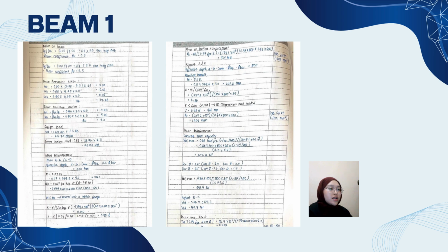For the shear force, lastly we check the shear resistance. We first ensure the concrete strut will not crush by calculating VRd,max at both 22 and 45 degree angles. The concrete capacity is much higher than our maximum shear force of 161.8 kN. To resist this shear, we design links. We decide to use R6-150 spacing. This ensures the beam is safe.